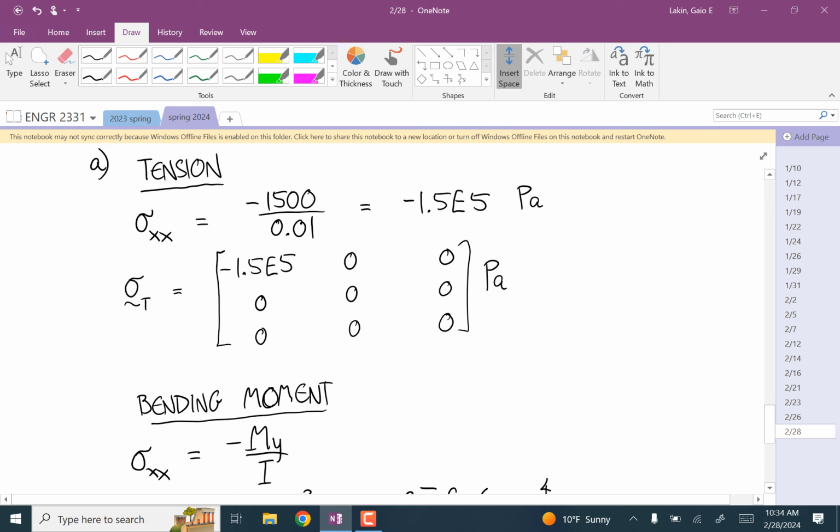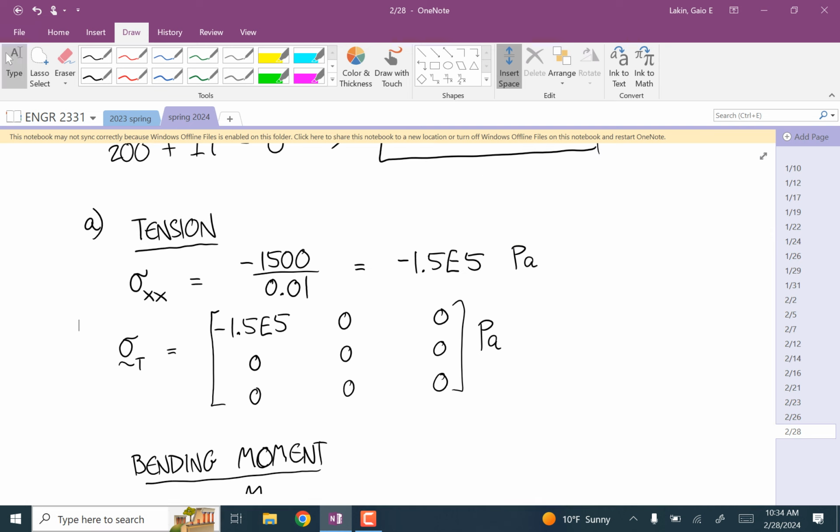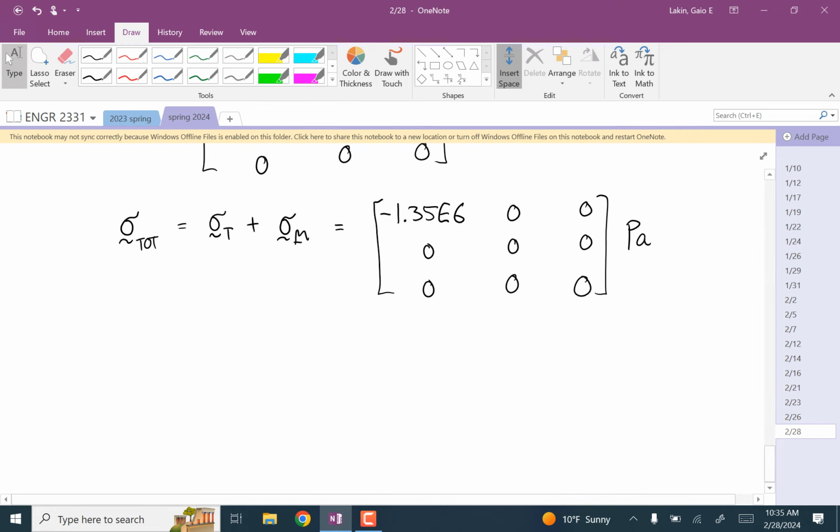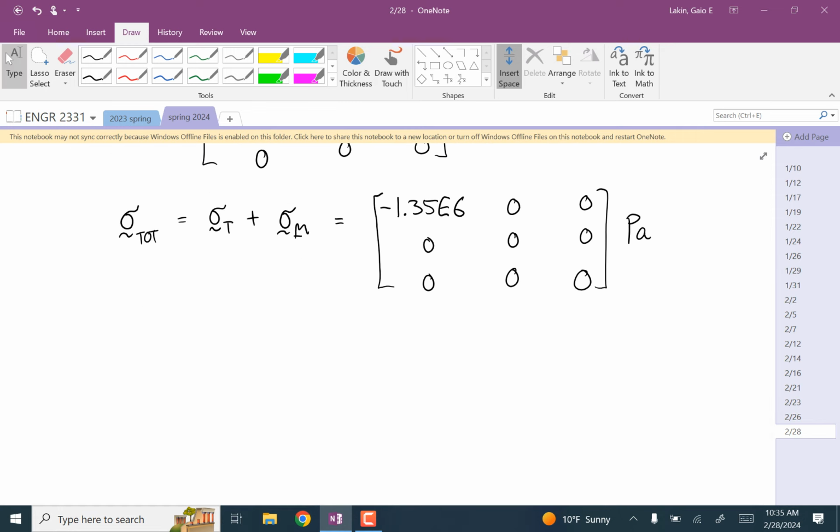Do you see that? There's a compressive stress due to the compressive force on it. But at the top of the beam, there's a tensile stress, and those two are in opposite directions. You could actually get those two stresses to offset each other completely, even if you have really big loads. But so I chose the bottom where those two are gonna add, and we're gonna have the biggest problem, if we're trying to figure out where this is gonna break.